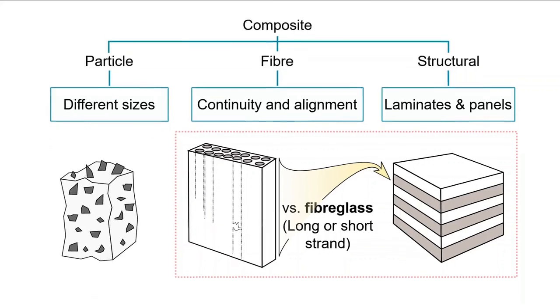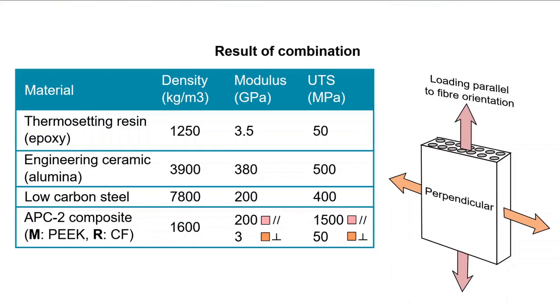matter. As described earlier, one strategy for formulating a viable composite is to use a matrix with relatively diminished properties compatible with a reinforcement with much higher properties. Here are some properties of thermosetting polymer compared against an engineering ceramic. The modulus of the ceramic is 2 orders of magnitude higher than the polymer, and the ultimate tensile strength a single order of magnitude higher.